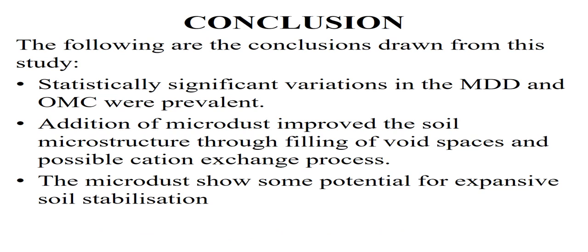So, based on the results obtained in this study, we can deduce that statistically significant variations in the maximum dry density and OMC were prevalent, with increase in both the compactive effort and microdust content.